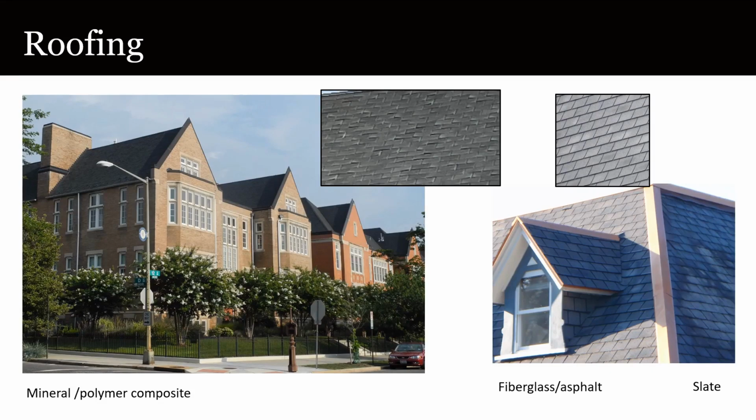Other materials, including concrete and tile, are also used to mimic slate, but for issues that can include cost and weight, and for some of those products, rather poor imitative appearance as well, they're much less frequently considered. While we do not usually consider fiberglass-based asphalt shingles as a substitute material for slate, there are situations where some of the fiberglass products that are designed to evoke the appearance of slate do a better job of approximating the size and proportion of smaller slates than the polymer products.